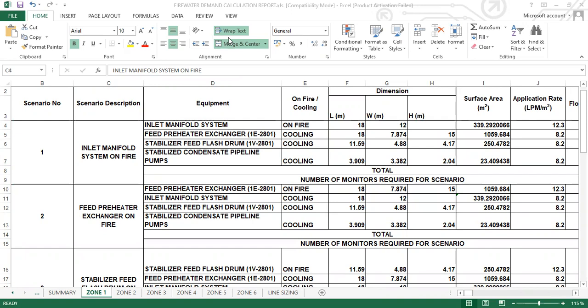Okay, apologies. So in this case, what we're trying to achieve is a gas plant. We don't want to put people, as much as possible, in the line of fire, because if there's a fire from a gas, you can have a jet fire, and the jet fire goes really far, and the effects are worse than if you're dealing with a fire from a liquid hydrocarbon. So as much as possible, we don't want to have people in here if we don't need to.